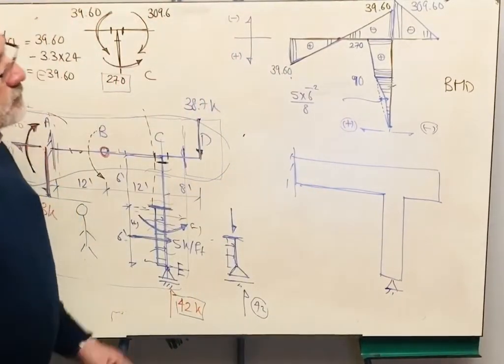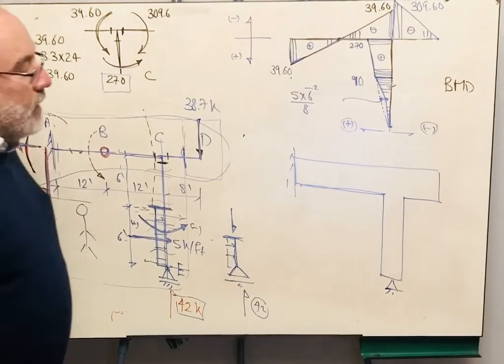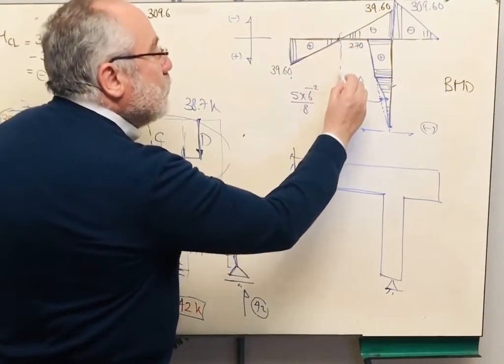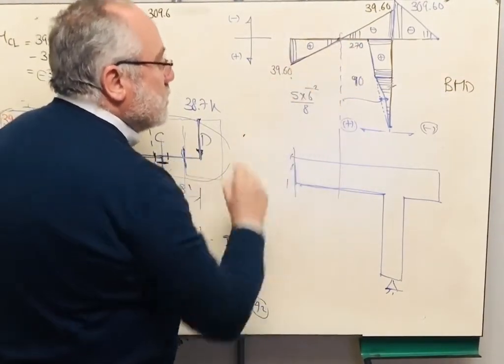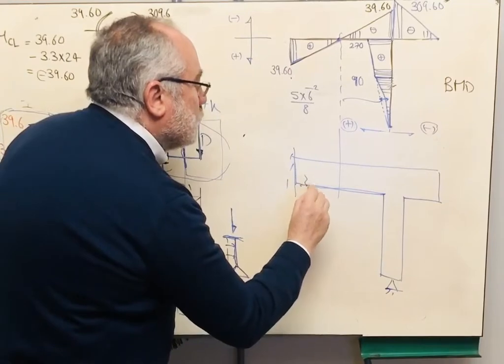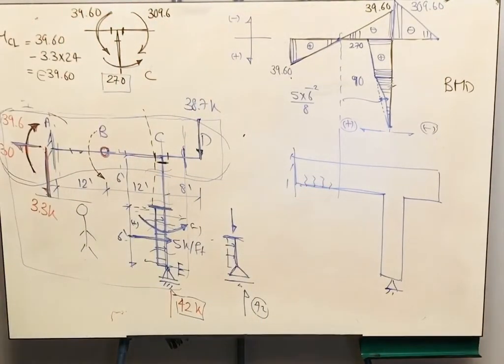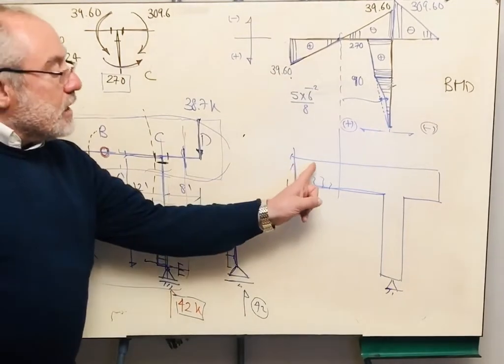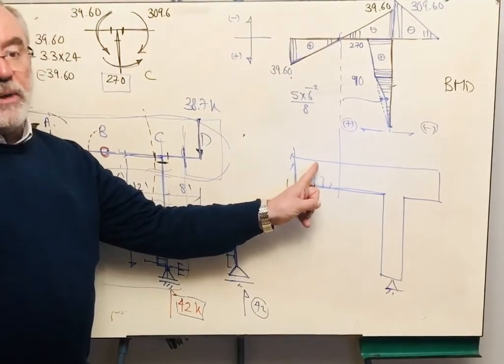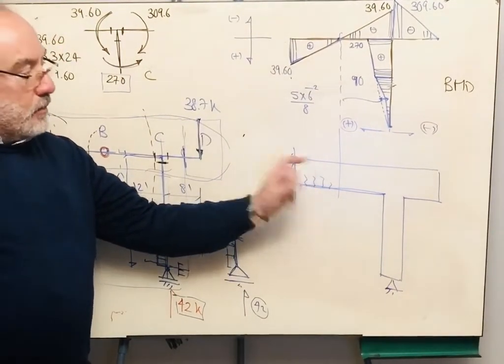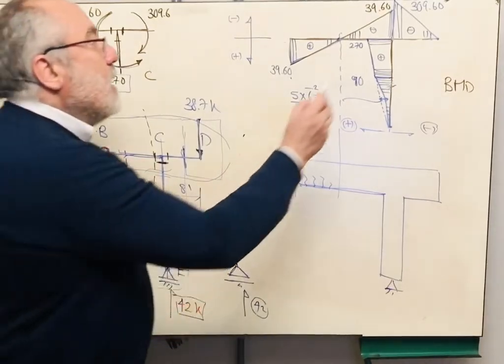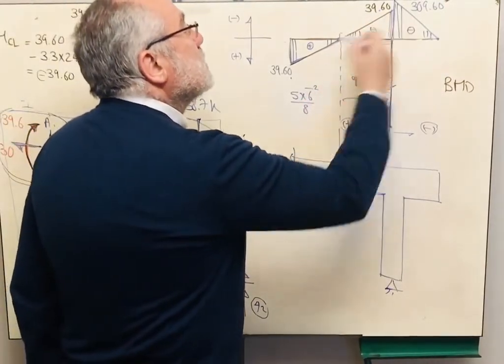Now, according to the bending moment diagram, since the bending moment diagram is drawn below the datum, it means that the concrete will start cracking here, because we are having tension on this side. Why will it not crack here? Because the concrete is strong in compression. It doesn't need any help. Okay? Now I'm having the bending moment now is reversed.